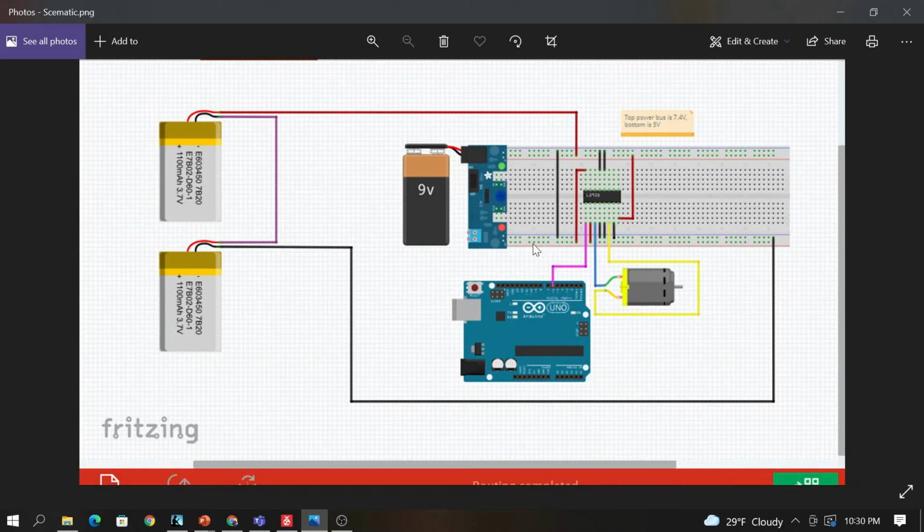The reason why I do that is because when you're changing duty cycles, if it drops below a certain voltage, it'll run the lower voltages, but it won't run the higher voltages, because we need to run this at a higher voltage. The motor is going to run at 9 volts. So if we're running at 100% or 75%, we need those 9 volts to power this motor efficiently. Otherwise, it's not going to work right. And when we drop down to 5 volts, we're using a lower duty cycle, less voltage. So that's why that works.